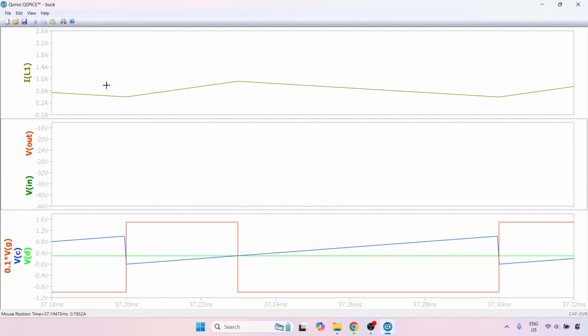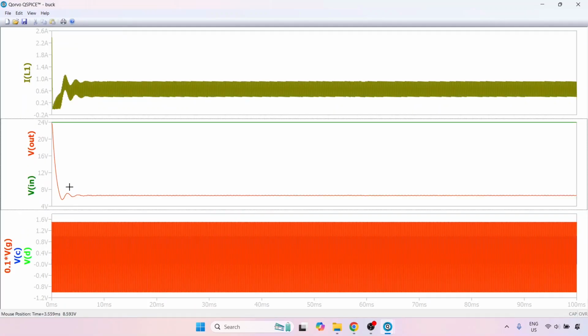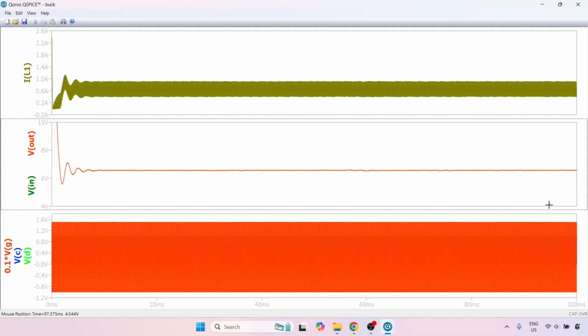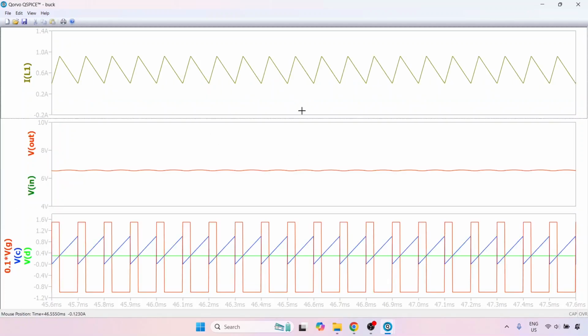And depending on the pulse width modulation, you will see here, let me just zoom in here as well, you will see that the output voltage has now decreased further. And that is because the output voltage is simply the duty ratio multiplied by the input voltage. And with the decreasing duty ratio, our output voltage will also decrease. So this therefore shows the pulse width modulation principle.